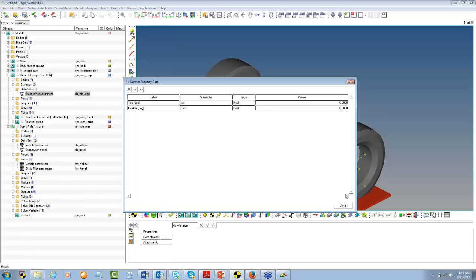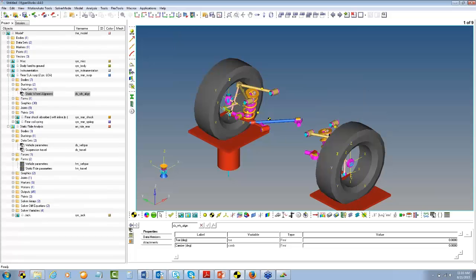So you can put in the toe and camber. The caster, however, you have to put in the points. You have to update these points, and that should pick up the caster value. But you can indeed put in the static camber and toe, if that was the question.